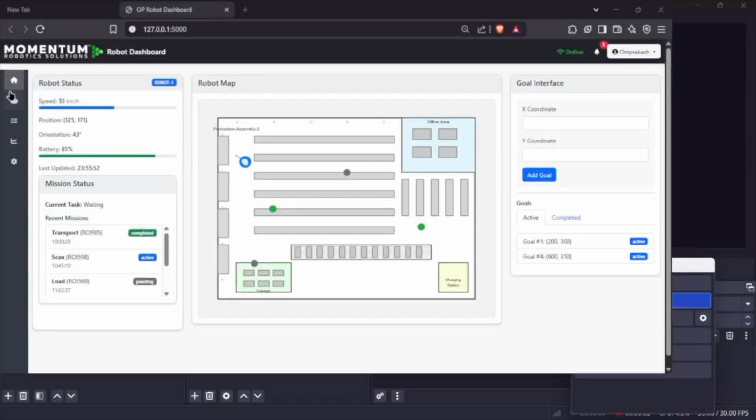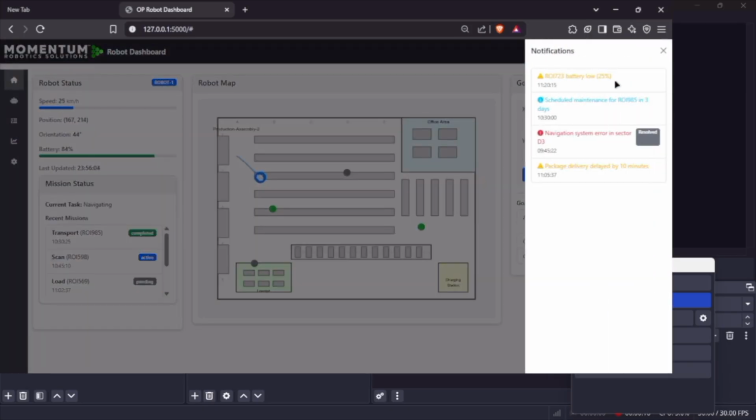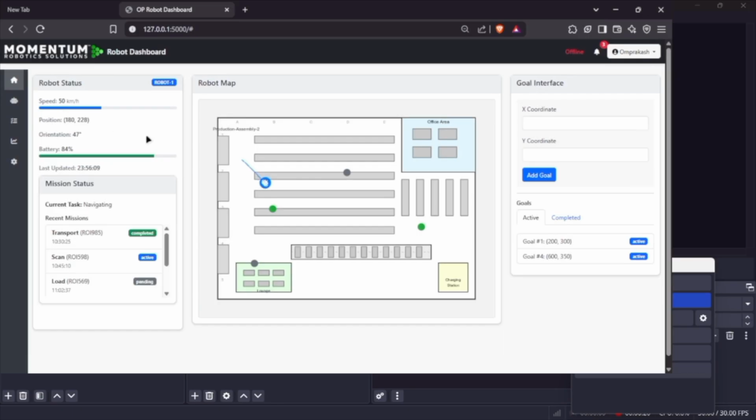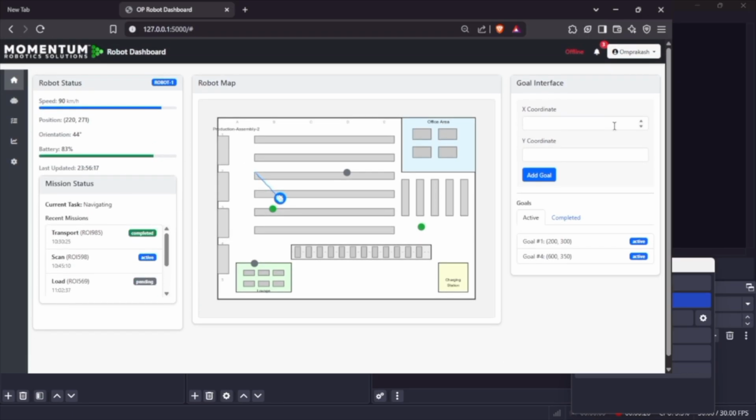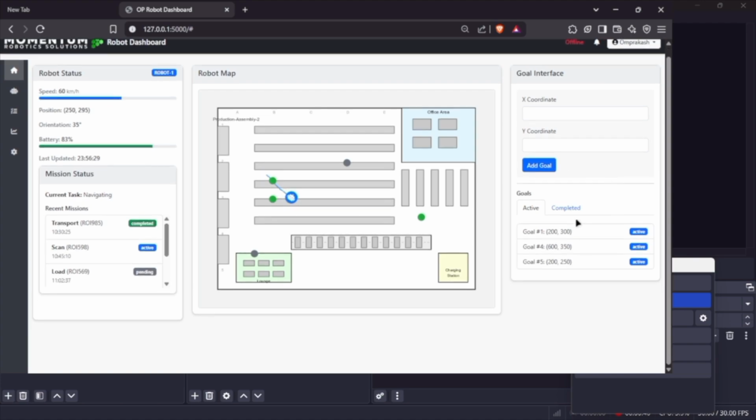This under-development version 2 of the control dashboard offers a clean UI and support for multiple robots. The technology behind the communication of the robots is MQTT. All the robots connect to one backend over MQTT. A FastAPI based backend is adopted to support the upcoming integrations with WMS or ERP systems.